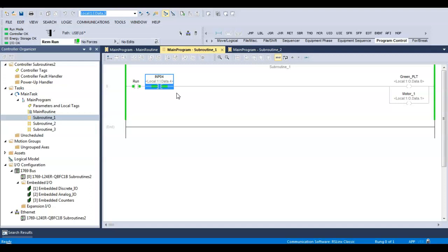It's just like if it's unconditional, you got no problem, because if it's unconditional, it's going to scan it every time in the main loop. If it is conditional though, if it's a conditional subroutine, and you want the output to be off when you leave the subroutine, then you better turn it off, or it won't run until it happens again. But it might be the situation. So you might say, we got a counter, and we can say if it's equal to this, we can use a limit and say if it's between this, right?